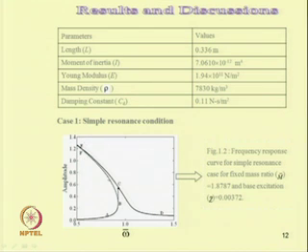With a higher value of damping, instead of ending at this point, the response may end at some other point before E. Then one may observe this jump down phenomenon also. So, while sweeping up the frequency, one can have a jump up phenomenon, and while sweeping down, one may have a jump down phenomenon.